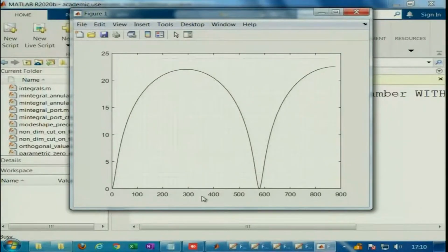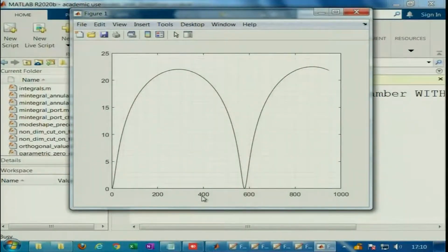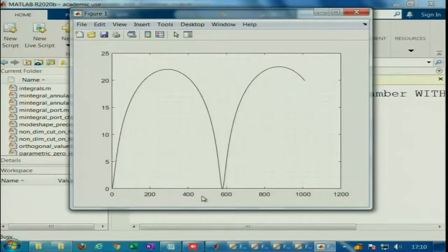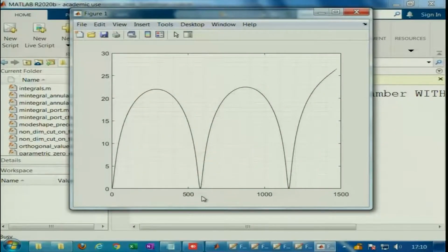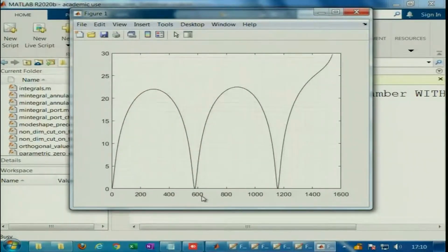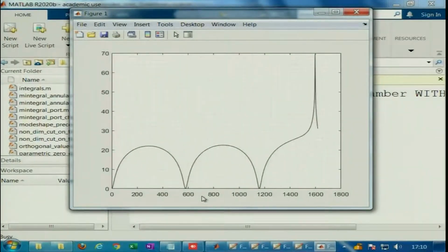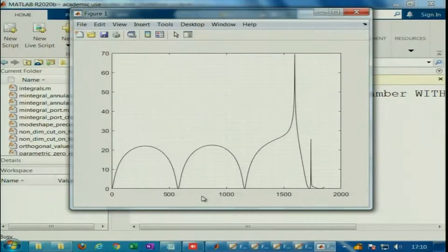You see this 3D effects will come sooner into the picture. And the other thing that I want to tell is that now here the expansion ratio is 5, so the area ratio is 25. So, 25 divided by 2 is 12.5, 20 times log of 12.5, because 20 times log of m by 2, that is the maximum transmission loss. So, wait for a while, we will do all these hand calculations, but before that you see a much collapse in the transmission loss spectrum much before.